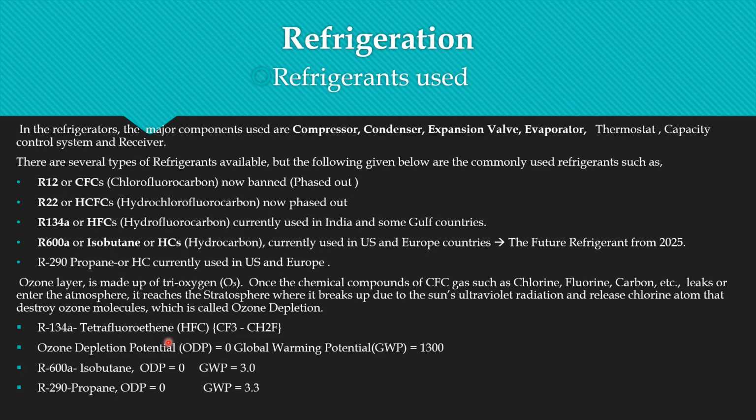R134A is tetrafluoroethane. The chemical formula is CF3CH2F. The ozone depletion potential is zero, but the global warming potential, as I said, GWP, is 1300. So it is to be banned soon. From 2025 onwards, this won't be available in India and Gulf countries also.